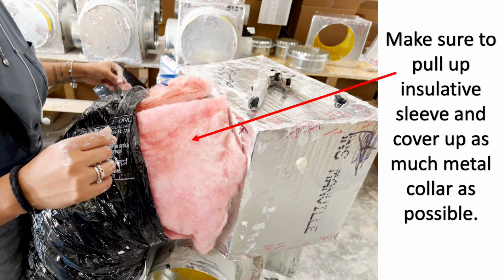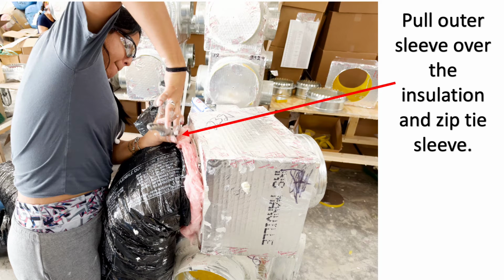Make sure to pull up the insulative sleeve and cover up as much metal collar as possible. Pull the outer sleeve over the insulation and zip tie the sleeve.